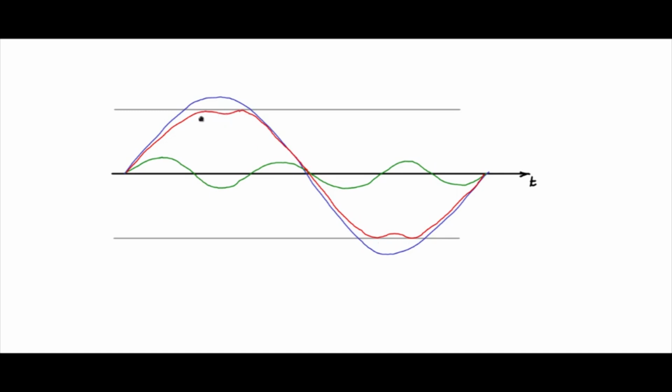Now this triplen compensated wave shape, the red one, if I use as a modulating signal, then it contains within it a fundamental which is more than 100%, and therefore I am able to get more than this 100% modulation possibility if I inject triplen.